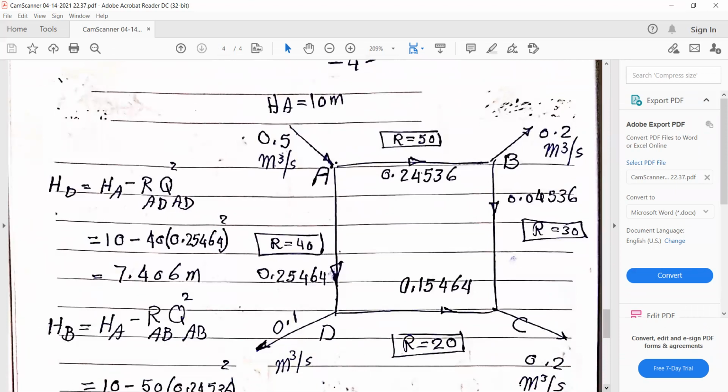Now, we come to the point where we would like to calculate the head. Usually, at the demand points the head is unknown, but the supply point has a certain head. So HA is a supply point here. We have HA equal 10 meters. Okay, if we have more than one supply point, then we have to make the so-called pseudo loop. I think it's beyond the scope of this course, so we'll not come to this for our problems. So we have only one supply point with given head 10 meters.